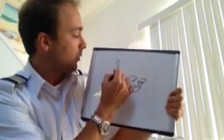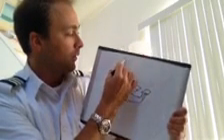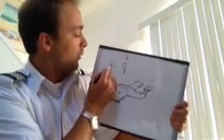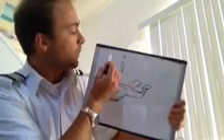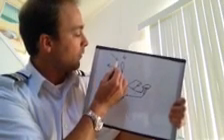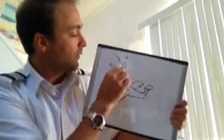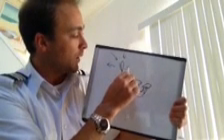at our vertical stabilizer from a top-down view, this was our relative wind when flying straight. Now we bank the aircraft, we have a horizontal component of lift pulling us into a turn. Our relative wind is now coming from a slight angle. This wind is going to hit this side of our control surface, causing it to be pushed this way. And it's a simple fact of weather vaning. The aircraft tries to weather vane itself back into the relative wind.